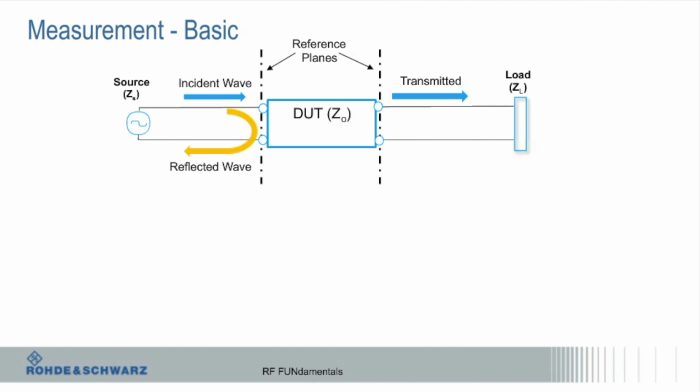And it's one of the cooler things about a VNA: most instruments, you don't get to pick where you measure. The front panel of that device is really your measurement reference plane. You can add losses and things like that to it, but it's not really designed to automatically figure that out for you. That's what, to me, is really cool about a VNA. Okay, I'm a nerd, so bear with me.